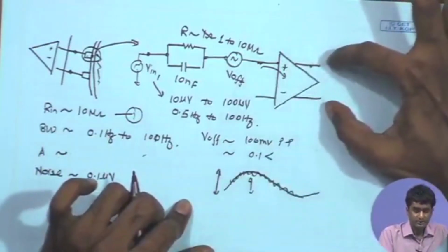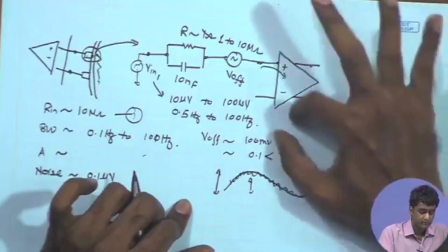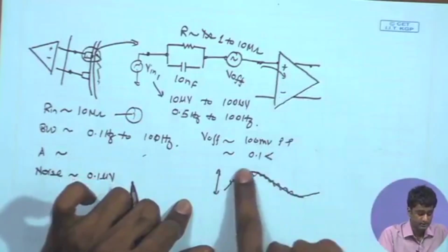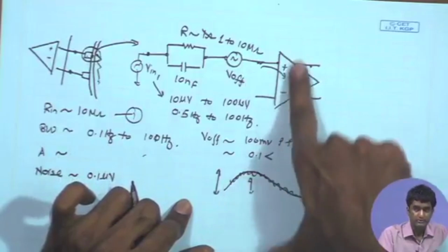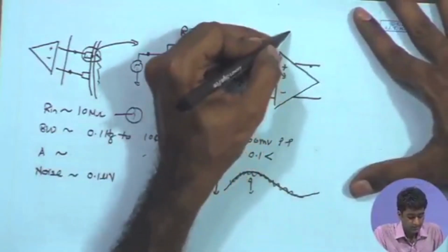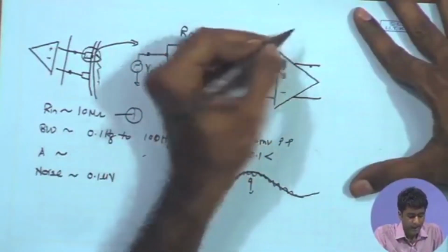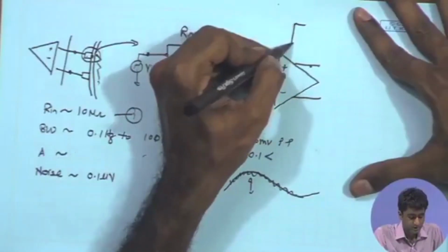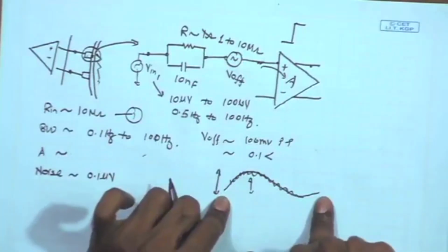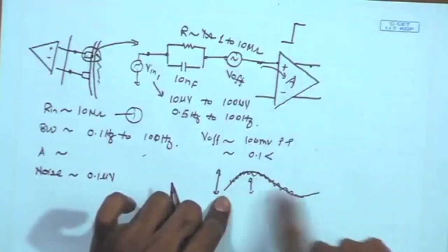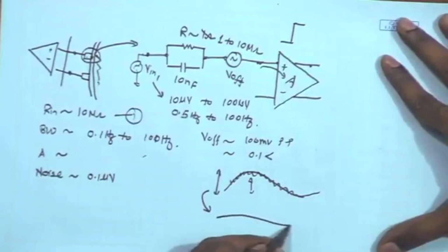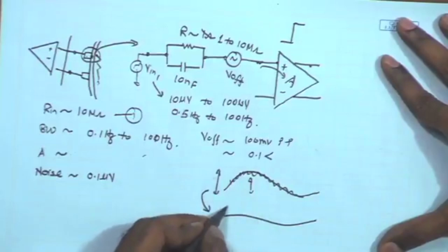We will see later as we progress along the design that there can be some ways in which you can incorporate a high pass filtering operation in the very first stage, so that this slowly varying signal can be cancelled out in the very first stage to a good extent. As a result, basically what we are trying to say is that the first stage is doing the job of an amplifier as well as a filter, which is allowing me to reject the undesired slowly varying signal to a good extent, so that at the output I am able to suppress this slowly varying signal.